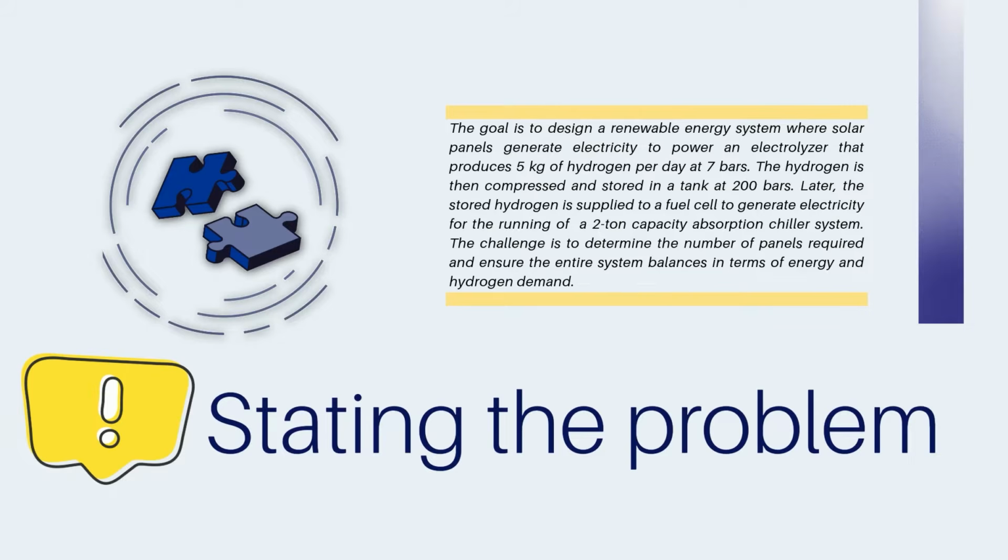The hydrogen is then compressed and stored in a tank at 200 bars. Later, the stored hydrogen is supplied to a fuel cell to generate electricity for the running of a 2-ton capacity absorption chiller system. The challenge is to determine the number of panels required and ensure that the entire system balances in terms of energy and hydrogen demand.